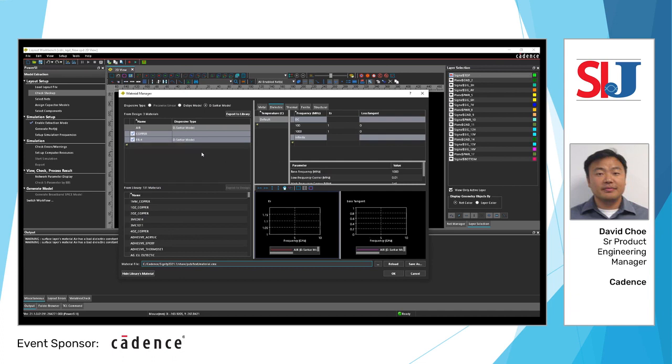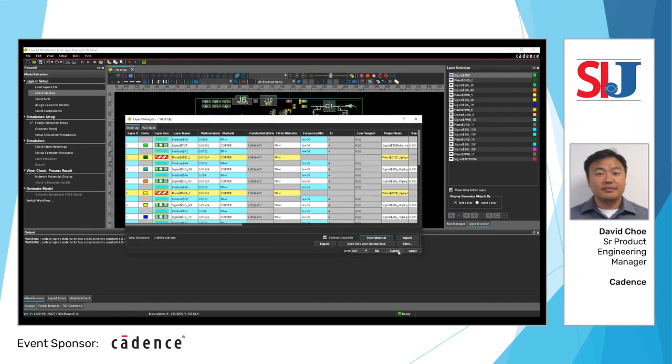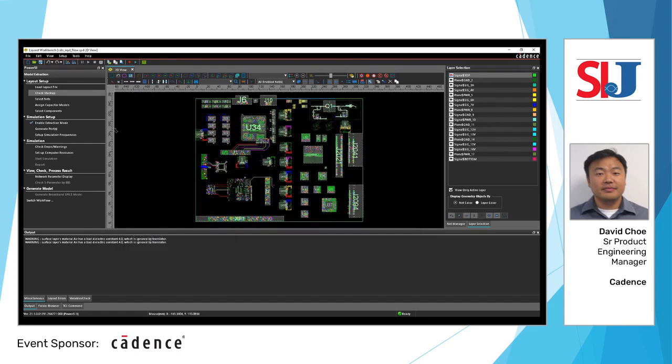You can view the materials as regular. So each one of these materials, you will have different loss tangents, dielectric constants, and metals, of course, will have different conductivities and such. Now, we're not going to make any changes here. We're going to the next step, which is selecting the nets that you wish to simulate.